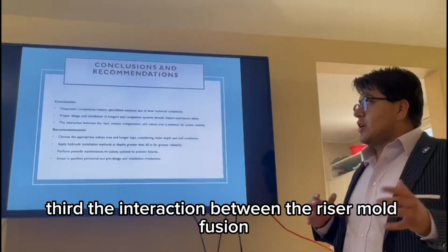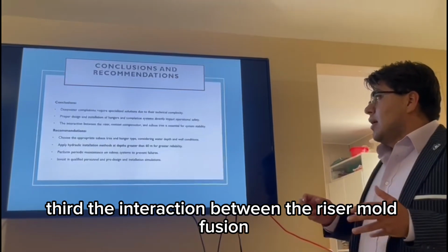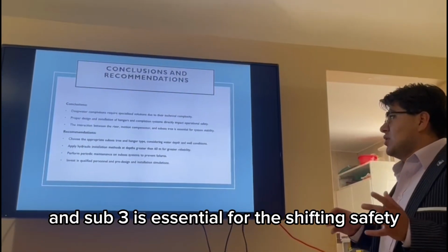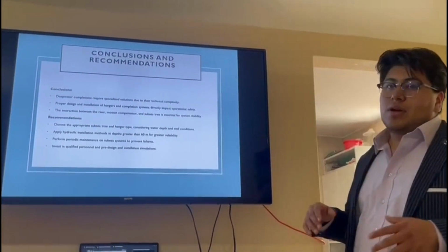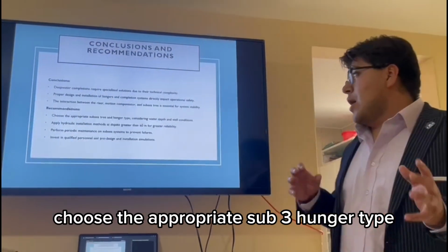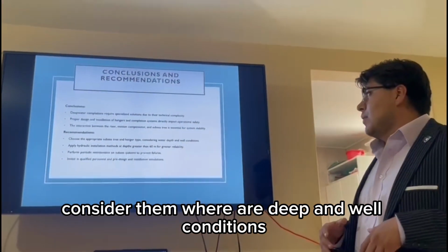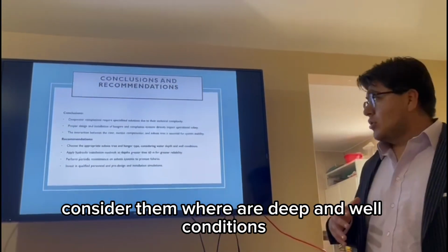Third, the interaction between the riser, motion compensator, and subsea tree is essential for system safety. Recommendation: choose the appropriate subsea hanger type, considering water depth and well conditions.